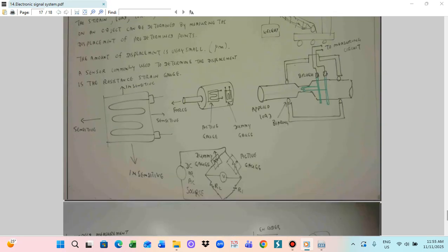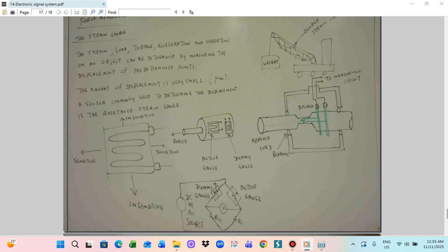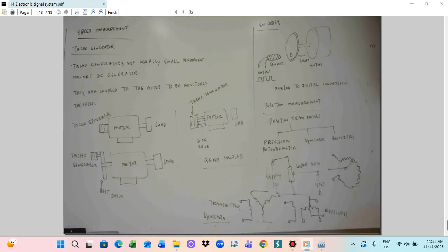In the meantime, you also need to measure the speed. Overspeed is also dangerous because of the bearings. When overspeed happens, the bearing can be melted out because the pressure is too high. So in the ship, the bearing is mostly the part usually damaged, especially in very stormy weather. Stormy weather means that normally the ships are like this. This is a ship here.